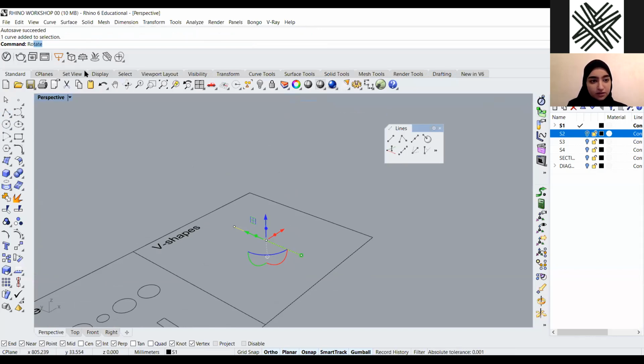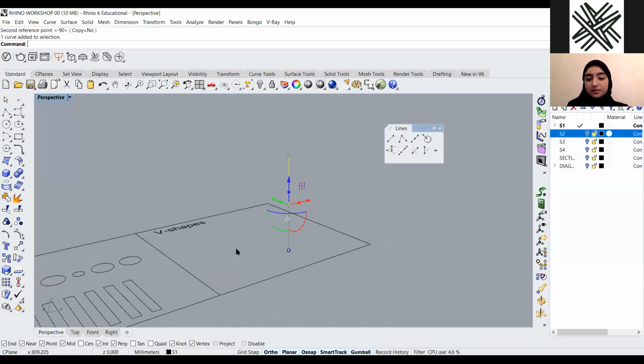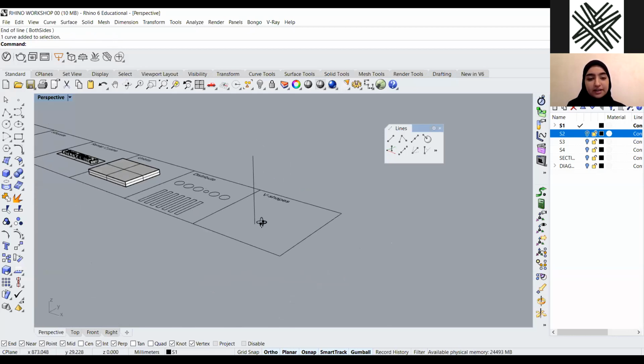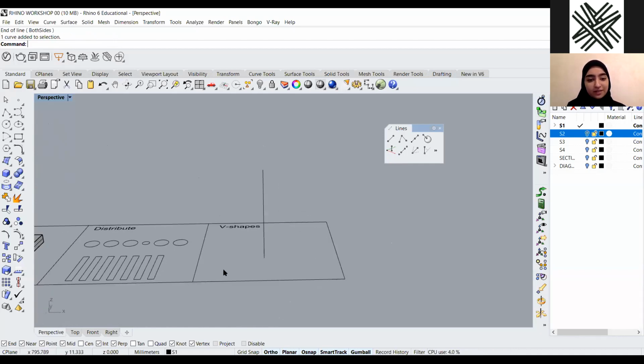and then I use rotate 3D, like that. But there's already a tool which is line vertical to CPlane. So just by clicking, simply you can create your vertical line. Because I know most people don't know about it, and they keep rotating the horizontal lines.